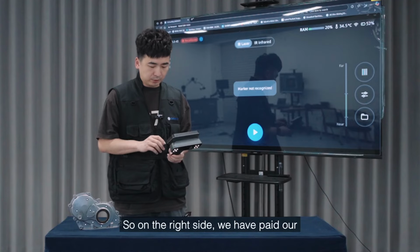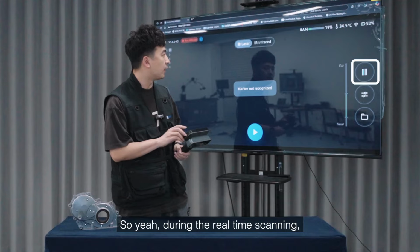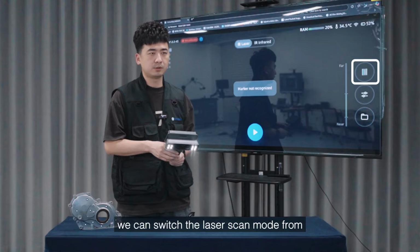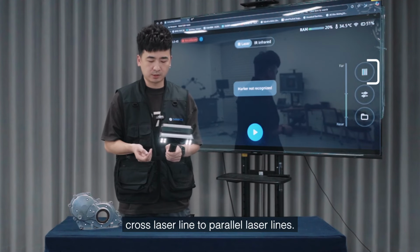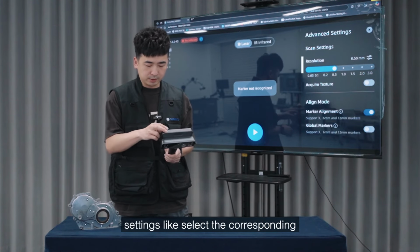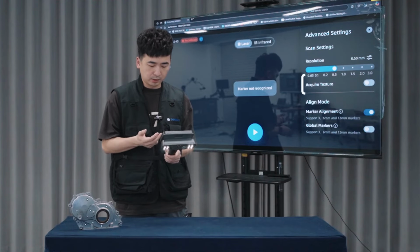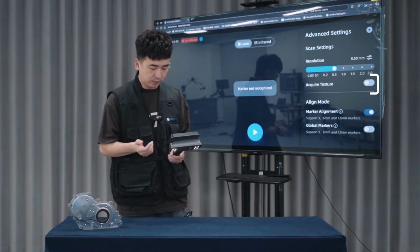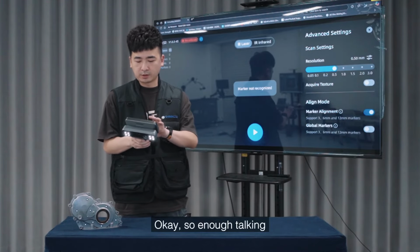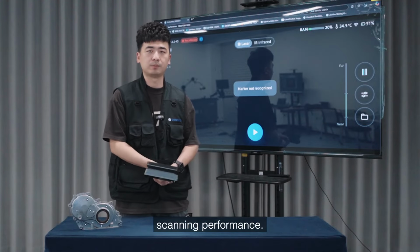On the right side, pay attention to the parallel icon. During real-time scanning, we can switch the laser scan mode from cross line to parallel laser lines. Then we need to adjust the advanced settings, like selecting the corresponding resolution for quick scanning, whether we need the texture, and, most importantly, we need to select the alignment mode. Okay, enough talking about this powerful device, so let's take a deep look at the real scanning performance.